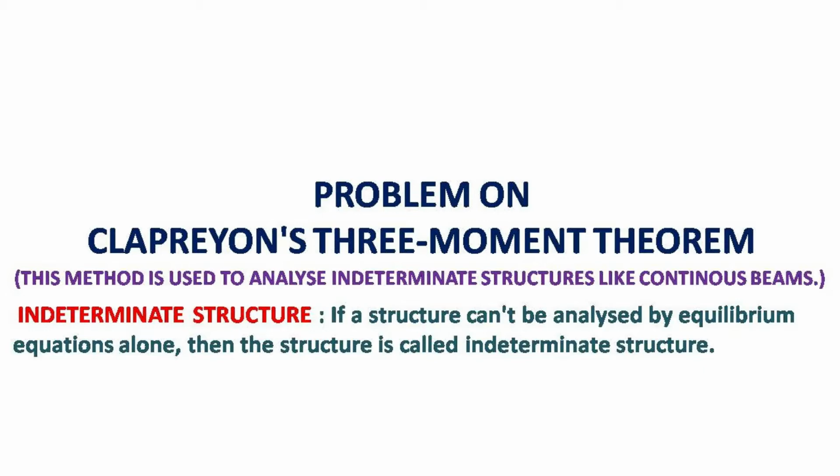Analysis means finding unknown forces and moments. That means we are finding shear forces and bending moments in the given continuous beam to draw the shear force diagram and bending moment diagram. Before going to analyze the problem, we should know what is the indeterminacy of the structure. A structure is called an indeterminate structure only when the structure can't be analyzed by equilibrium equations alone. We need additional equations to analyze these types of structures.